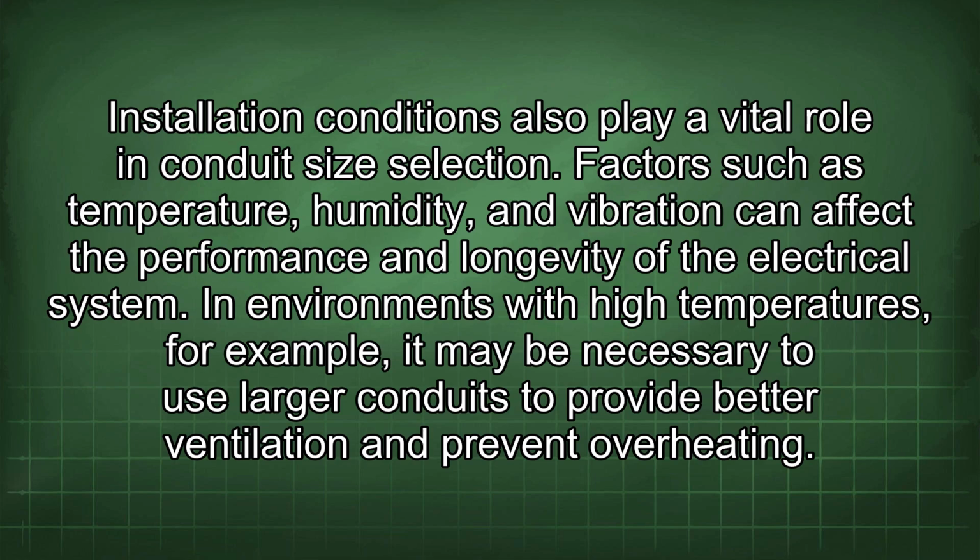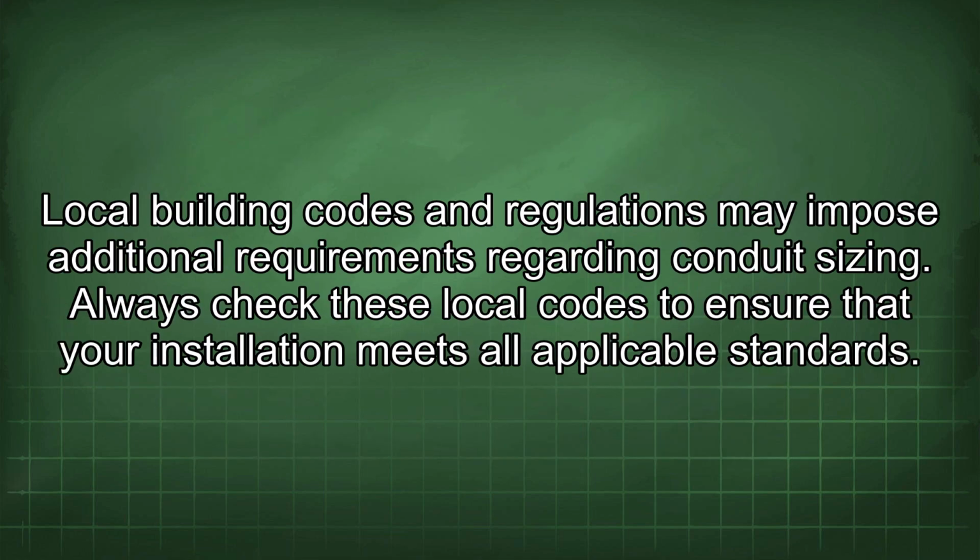In environments with high temperatures, for example, it may be necessary to use larger conduits to provide better ventilation and prevent overheating. Local building codes and regulations may impose additional requirements regarding conduit sizing. Always check these local codes to ensure that your installation meets all applicable standards.